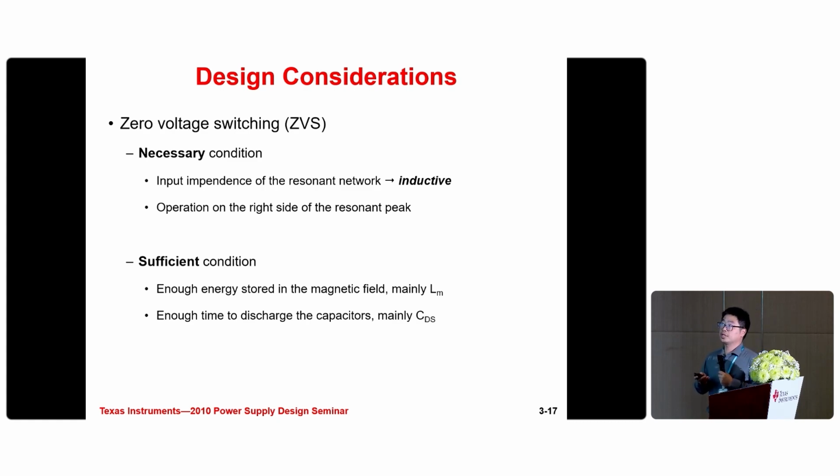The sufficient condition is that we need to store enough energy mainly in the magnetizing inductor. This magnetizing current will discharge the capacitors, mainly the CDS. Another thing is we should have enough time, that means the dead time for the discharge.